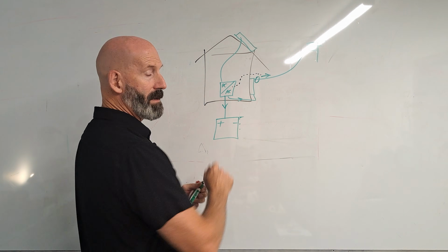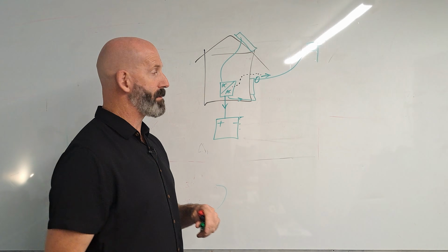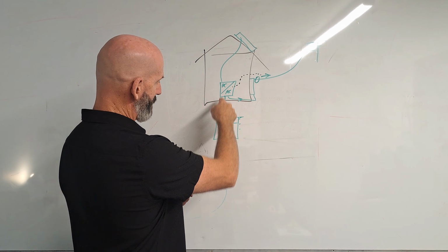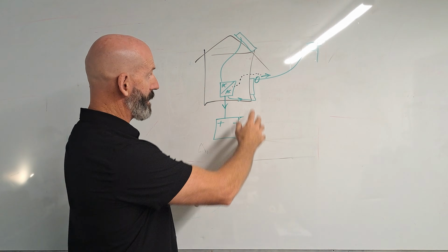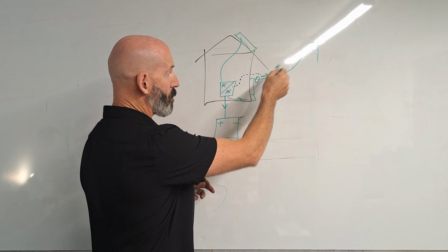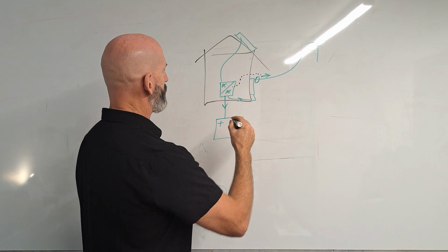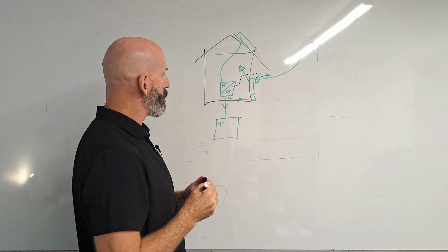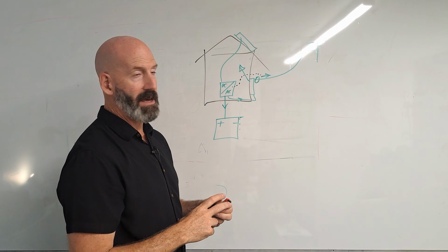If you have this same energy meter and it's, let's say, export limited, what that does is see any power going this way. It says, battery's full, I can't put it there. I'm going to ramp down the production capacity of my inverter so that I don't feed anything back to the grid. So it's just matching whatever's going into the house from the switchboard. It's just going to make sure it only produces that much.